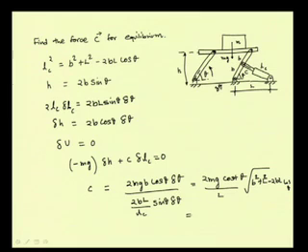If we simplify this further, we have it as 2 mg cot theta times the root of 1 plus (b by L) squared minus 2 b by L cos theta. So, this expression now gives the value of the force that has to be supplied by the hydraulic cylinder at this joint in order to support this weight at this height.